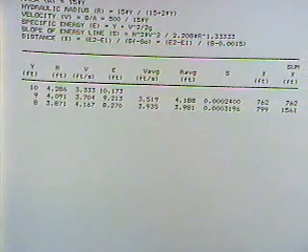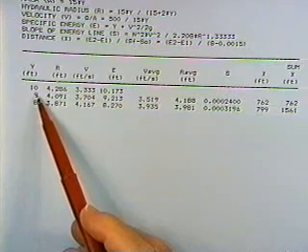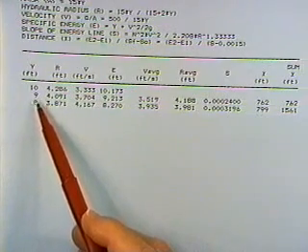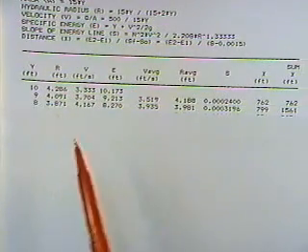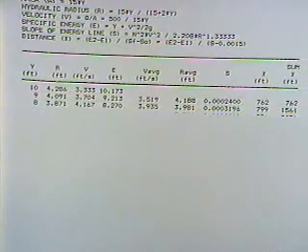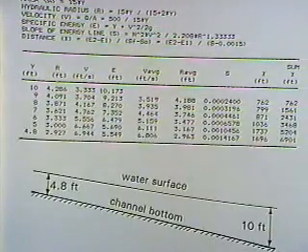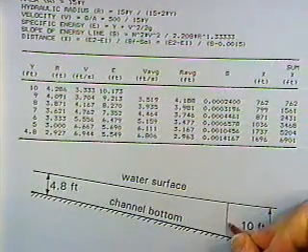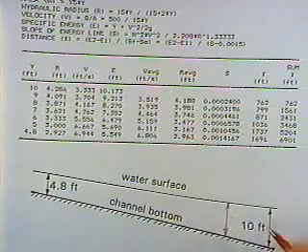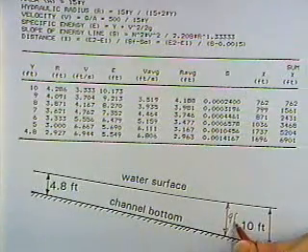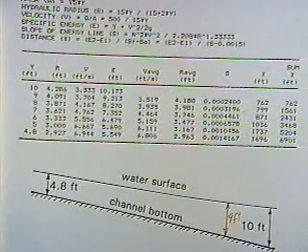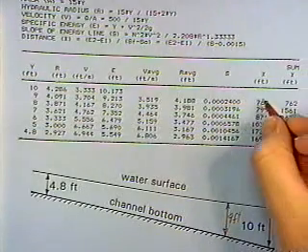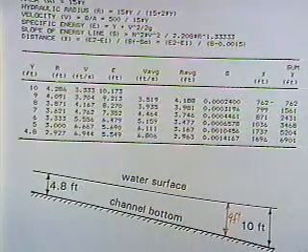So we go down another line and look at one section where the depth is 9 feet, at another section the depth is 8 feet, and we do the same computations all over again. And we just keep going. So there's 10 feet, someplace the depth is 9 feet, and I used the energy equation and computed a value of 762.